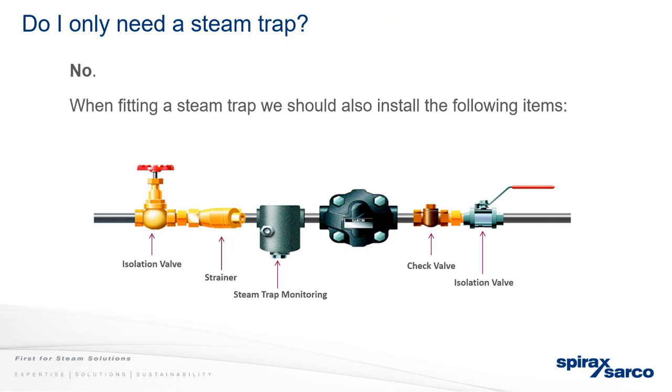We have what we call the APT, which is our automatic pump trap. We also have an MFP, which is a mechanical pump trap, both of which use a motive steam connection. So you connect raw steam directly to a motive port.